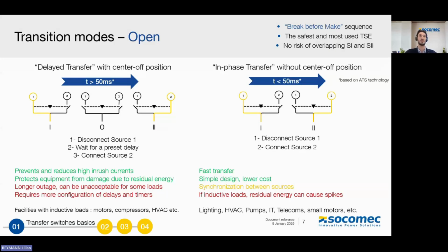The time transfer is usually above 50 milliseconds. The sequence is, firstly, the first source will disconnect. We will wait for a preset delay. You can set it up in the controller if it's an automatic switch. Otherwise, you can wait manually if it's a manual transfer switch.